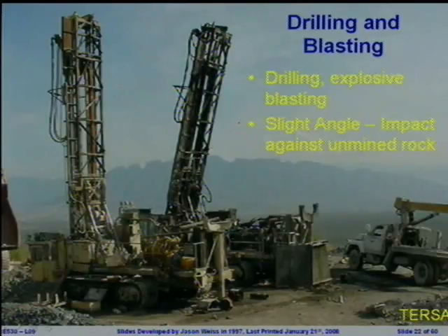drilling and blasting. So much like we saw with the manufacture of materials to go through the cement kiln, here they're going to be drilling a series of holes. Those holes are typically going to be filled. When I say filled, they're not filled up to the top. We're not filling them to the brim with a charge. They're typically going to be filled up about 15 to 20% with an explosive, and then that's going to be